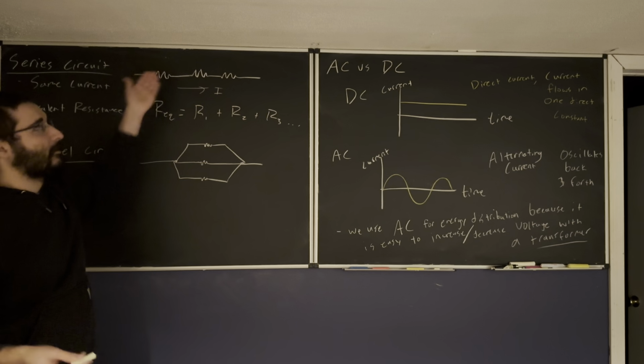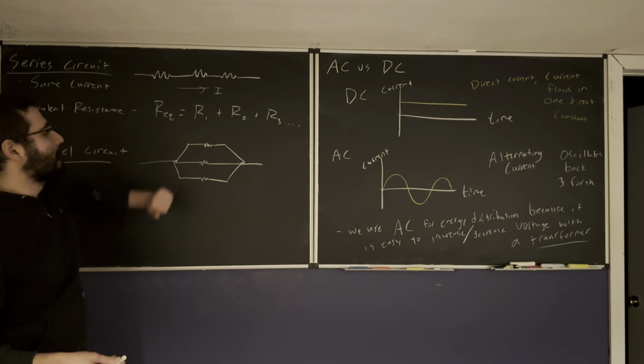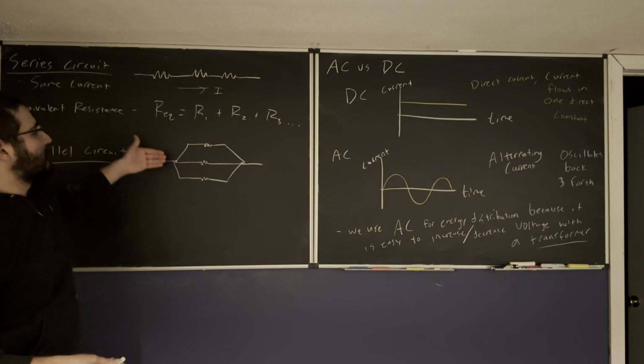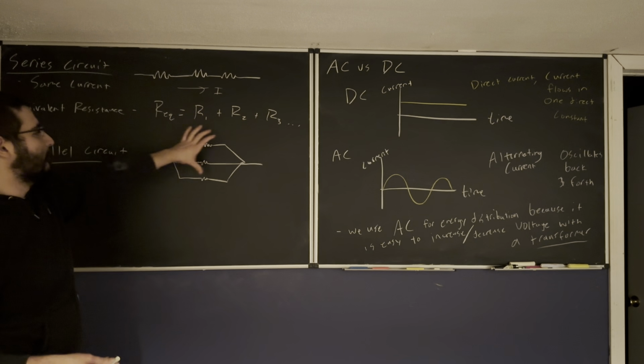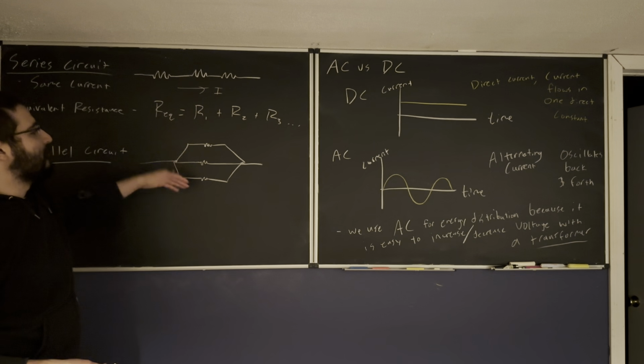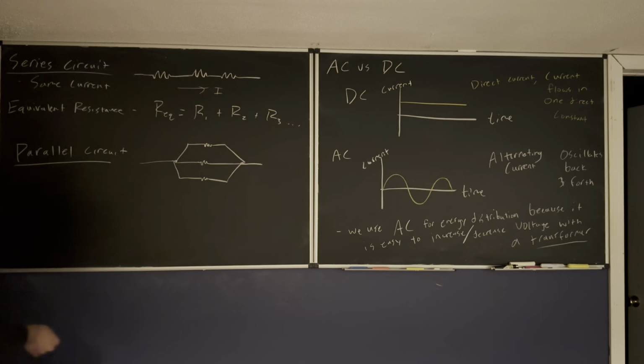All right, and then you can't even figure out which bulb is actually out. That's what makes it even more annoying. But for resistors in parallel, if one of the bulbs goes out, that just means the electricity doesn't flow through that branch. Okay, so in this case, I have multiple branches. Say I have 3 light bulbs. If the middle bulb burns out, the other 2 stay on.